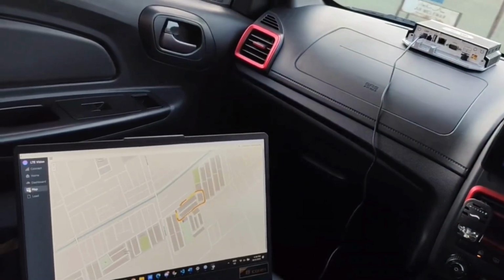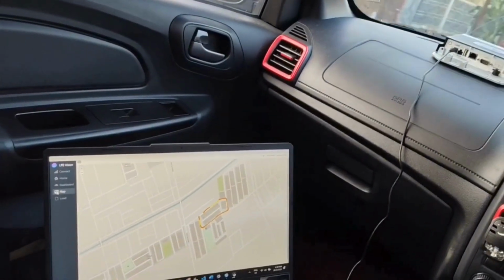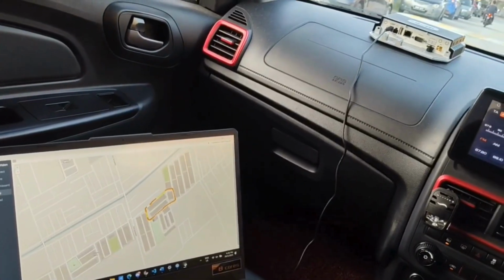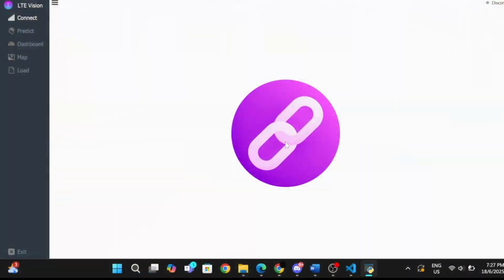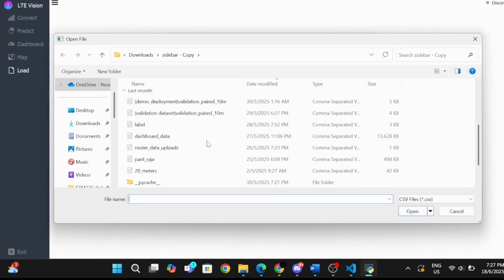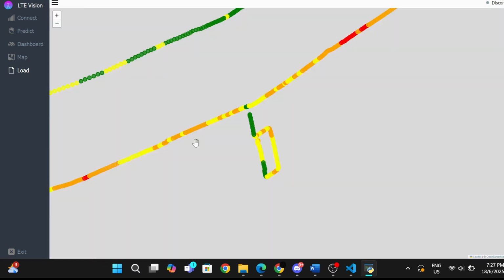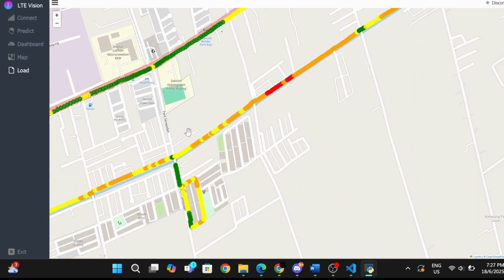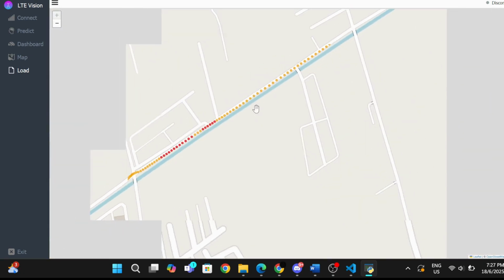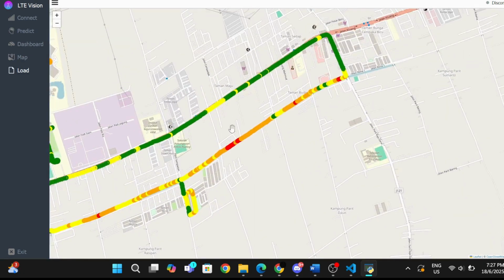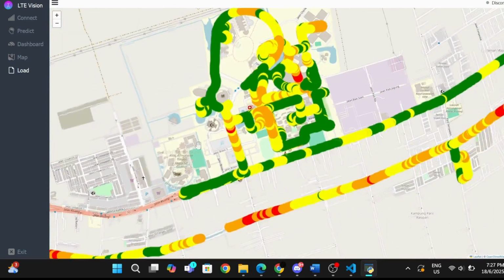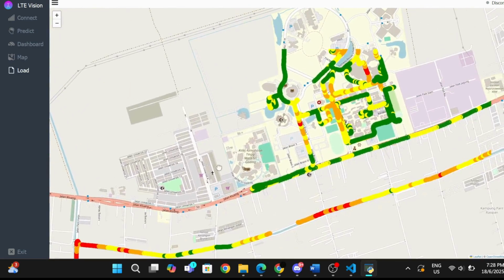This makes the dashboard an efficient tool for monitoring LTE network coverage, especially during drive tests due to its real-time capabilities. The software user interface can also generate heat maps from collected data for post-analysis purposes. In this case, the input file must be in CSV format and include latitude, longitude, and RSRP values. This feature allows users to visually identify areas of varying signal strength across a geographical region. This can be helpful for in-depth historical trend analysis and long-term network planning, complementing the software's real-time heat map capabilities, which offer immediate insights into current network conditions.